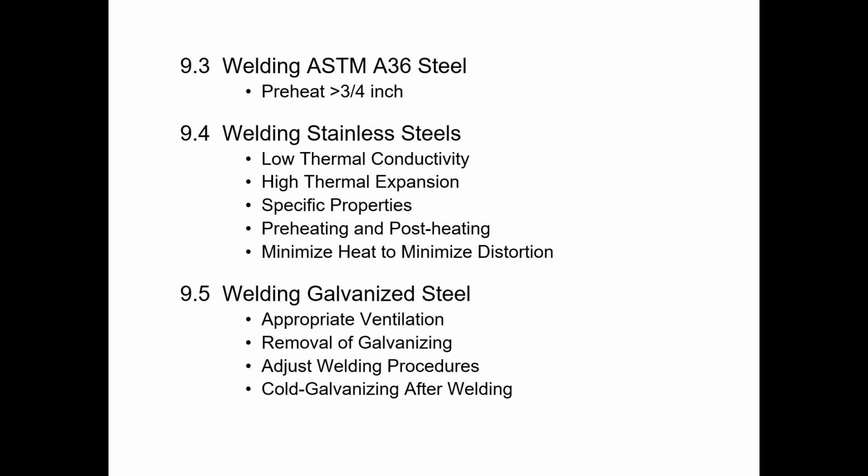I don't know that I've seen this very often, that a precast plant is welding stainless steel, but it is possible. You can weld stainless steel. It's a lot more difficult. It's a lot more involved process. Stainless steel has very low thermal conductivity, but very high thermal expansion. So what that means is heat doesn't necessarily pass through it very easily or quickly, but when it's exposed to heat, the material expands much more compared to regular carbon steel.